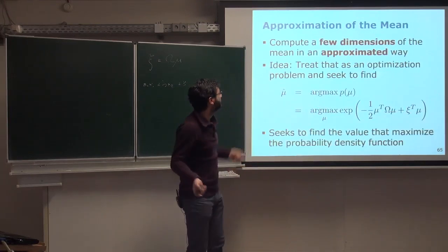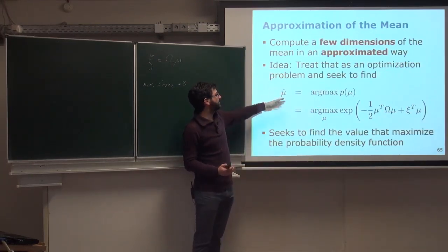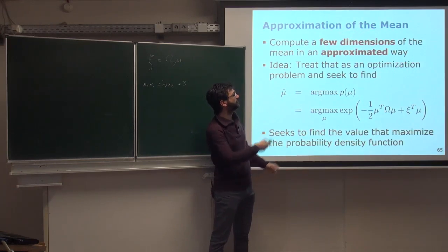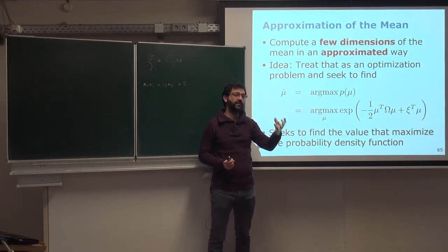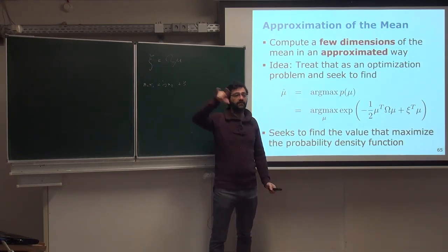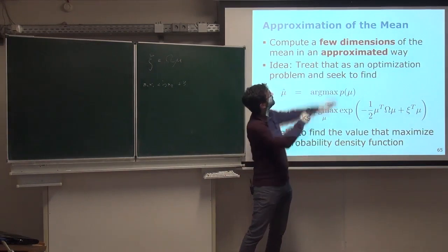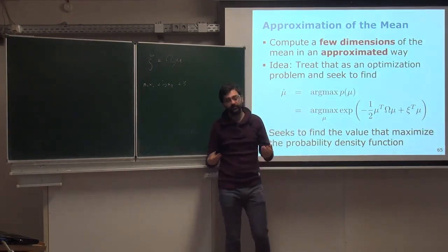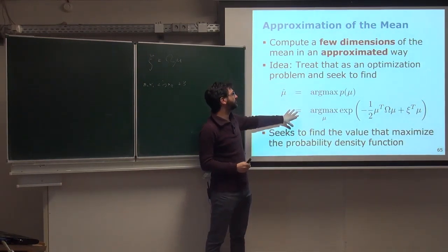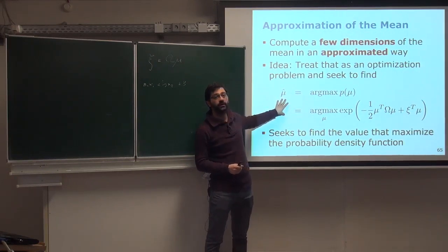So what we do is we formalize, or we cast this as an optimization problem, where we say we need to compute here normally 3 dimensions because that's the one that you need for linearizing. If you need to do a linearization for the state vector, you just need to solve for x, y, and theta of the robot, or if you're in 3D with the z and the different angles. If we need to linearize all around some landmarks, you can also solve for just a few of them. But in general, you can either decide to solve for the one that you need, or you can decide to solve it for everything.